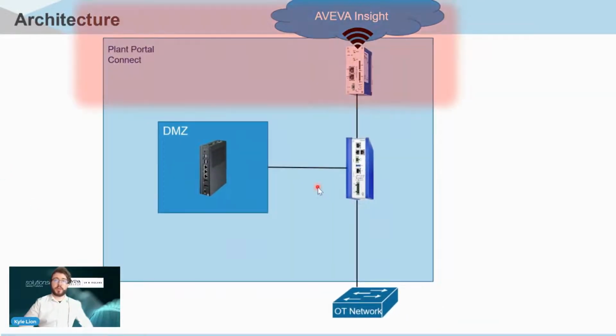So what we've got with this architecture here is we can actually implement zones of privilege. We can see that we've got the red zone, which is the zone of least trust, because that is our connection to the wider internet. We've got our amber zone here with our DMZ, which has slightly more privilege and more trust. And then we have our OT layer. This is where the actual data is coming from, and that is the zone of most privilege.